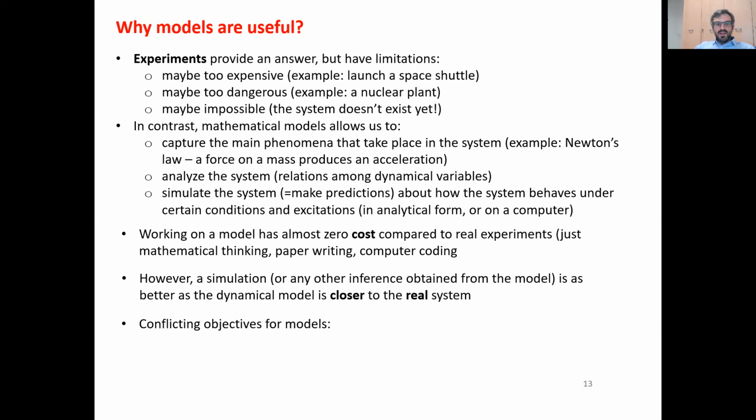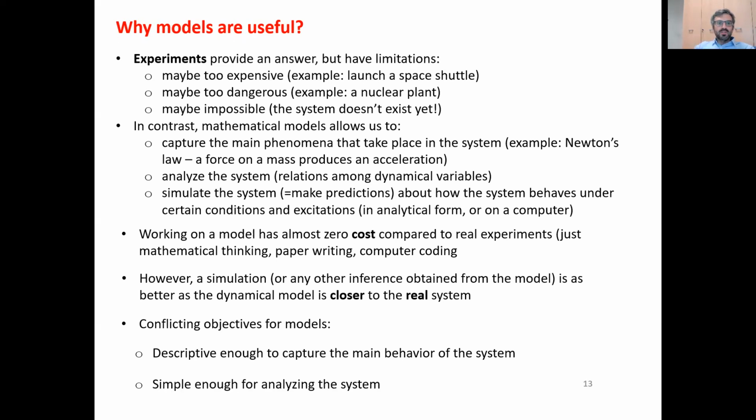But then we have some conflicting objectives for the models. The model needs to be descriptive enough to capture the main behavior of the system, all the relevant things: elasticity in the transmission, frictions, non-idealities, and so on, but also simple enough to analyze the system. If you have a very complex model and you want to compute the transfer function, it might take quite a lot of time to compute, or could have a big number of poles.